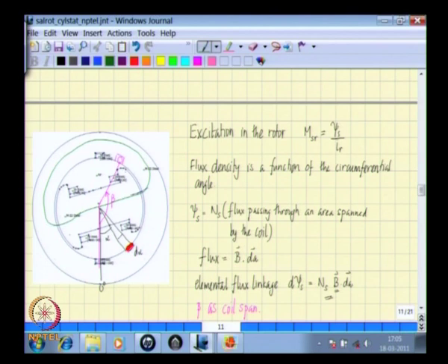We had earlier seen a flux density distribution that is there in this system. We saw how the flux lines go. So these flux lines are going to go mainly here, and we have also seen that the MMF, or the value of H that is dropped along this flux path, is predominantly concentrated in the air gaps, and we had derived an expression for that.